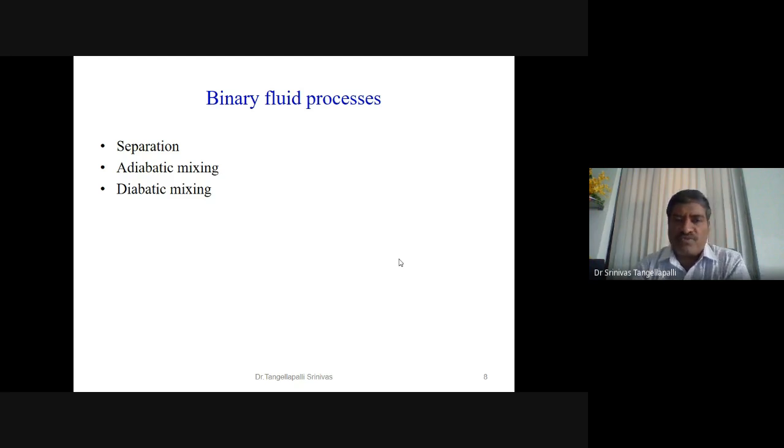What two fluids? One is a vapor and the second is a weak mixture, which is a liquid solution. If we send the vapor directly into condensation, it's difficult to condense at our climatic conditions, the sink conditions, because it needs either high pressure or very low temperature.